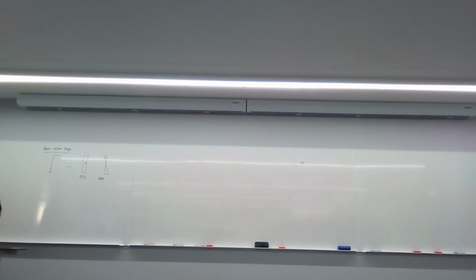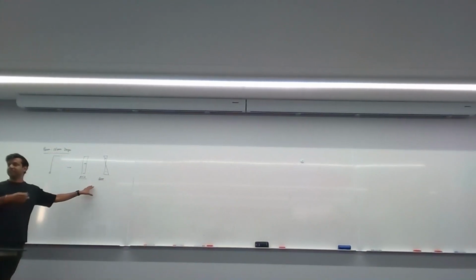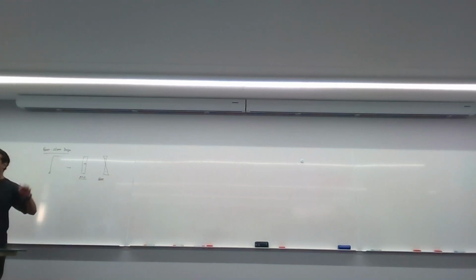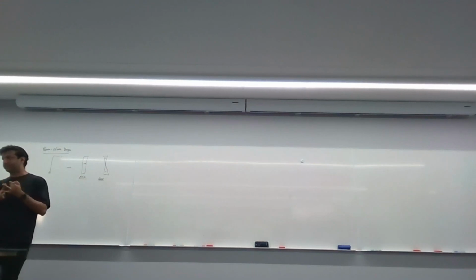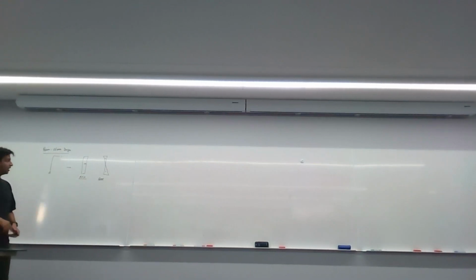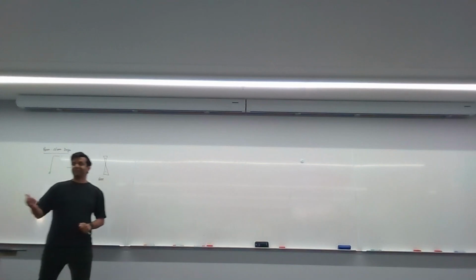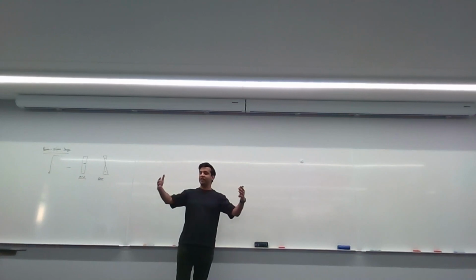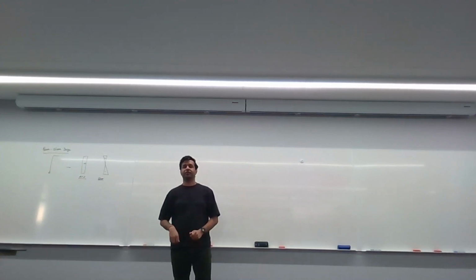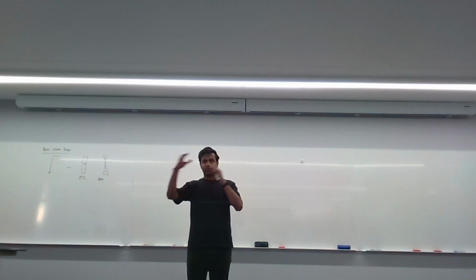At the end of the day, for any beam column question that you get, always try to identify what are the forces being applied on the element that you're designing. Sometimes the question might start off by giving you this huge building and say, design this particular column, and this is the bending moment and shear force or axial force diagram for that column. Most of the time they don't give that to you because that'd be too nice of them. So whatever loading they might give you, you use the different workshops that you've done in the course so far to try and calculate what those forces are.